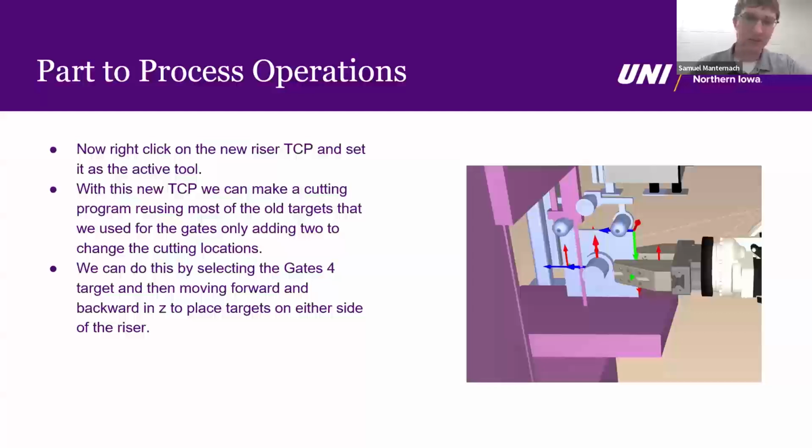In actual finishing operations, a bandsaw is not always going to be the best option for doing these cutoff operations. You can see in the image on the right, it looks like we're about to crash into that bandsaw blade. However, after this point that we would have done this operation, our gates would have been cut off along with those two risers and our pouring basin from the first cut. So those are technically not there in our imagination, but they are there in our actual physical cell. And then when we perform this cut in real life, those gates wouldn't be there as well.